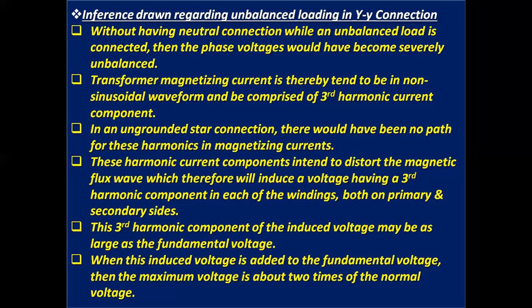This third harmonic component of the induced voltage may be as large as the fundamental voltage. When this induced voltage is added to the fundamental voltage, then the maximum voltage is about 2 times the normal voltage.